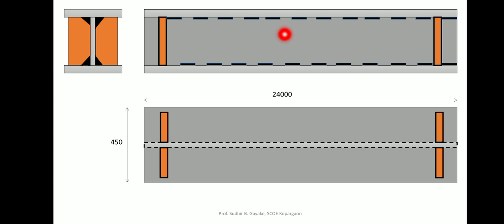This is the side elevation and this is your top view, where stiffeners are provided only at the ends. Both stiffeners are provided only at the ends because the maximum force acts as shear force or reaction exactly at the support, and for the center span the shear force is lesser or zero. Therefore there is no requirement of stiffener at center span. Usually in condition 2 there may be a requirement of stiffener at center span also if concentrated loads are there, and for condition 3 there will be a requirement of stiffeners throughout the span, but provided in alternate fashion.